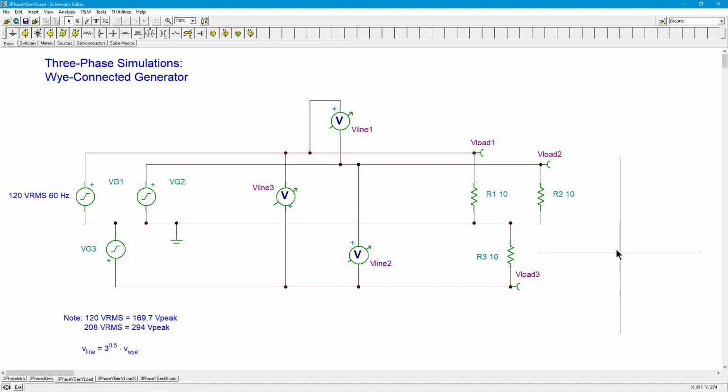So you have a magnitude of 120 here at 0, and a magnitude of 120 over here at 300, or minus 60 if you prefer. The magnitudes are identical, so the resultant is going to have an angle in between those two. That's 0, that's minus 60, so we're looking at a negative 30-degree shift at some larger magnitude. That 120 turns into 208 RMS, or 170 peak turns into just under 300 peak. So that's what we have for that.